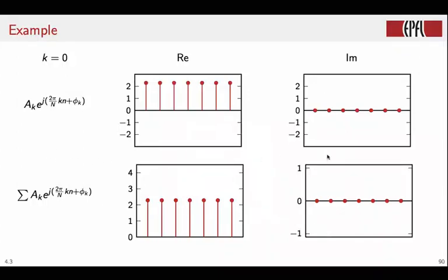In the first line, we will show the output of each generator in turn, starting for k equal to 0 up to k equal to 6. And here on the bottom line, we will show the cumulative sum of the outputs as k proceeds from 0 to 6. So the first generator is the one for k equal to 0, so the frequency is 0, and the output will be simply a constant. As a matter of fact, the value of this constant will be equal to a of 0. And so the cumulative sum now has only one term, so the output at this point will look like a constant.